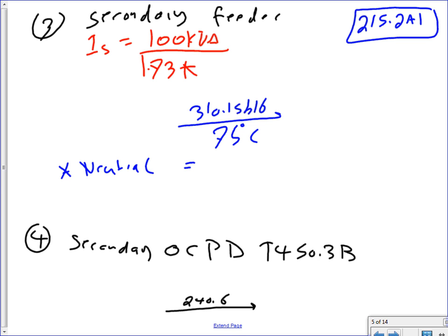When you guys go to Revit and you start circuiting to the transformer, you have to understand the transformer is going to have 2 distribution systems: one based on 480 and one based on 208. When we start circuiting, you pick up the transformer and circuit it to the panel, and it says, Chad, well, it's not circuiting. Well, because you didn't assign a 480 to it on the primary side. If you want to circuit to it, it has to be assigned to 480.